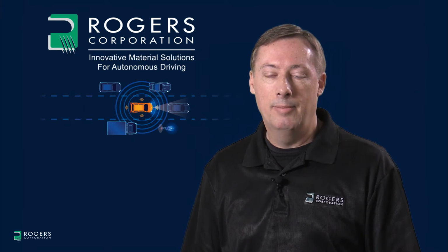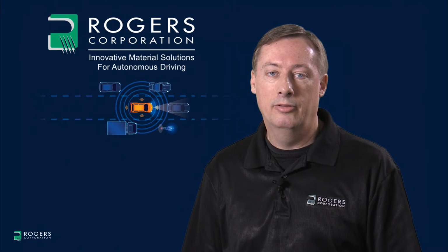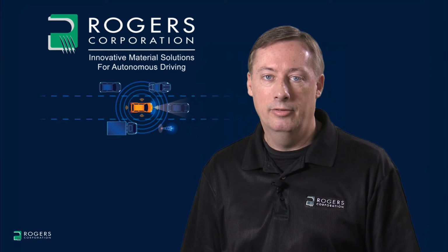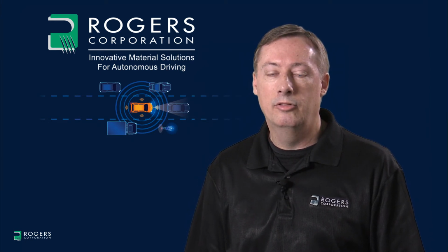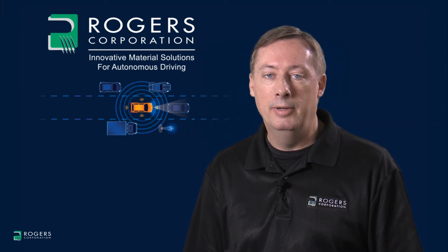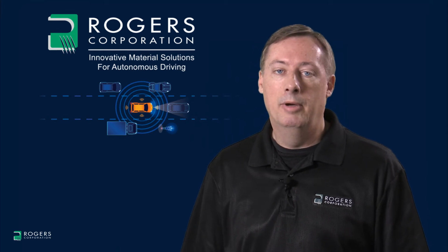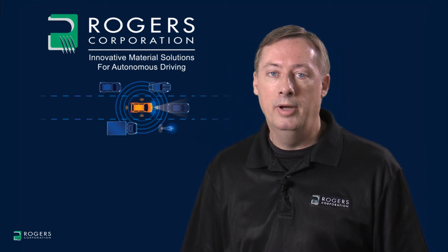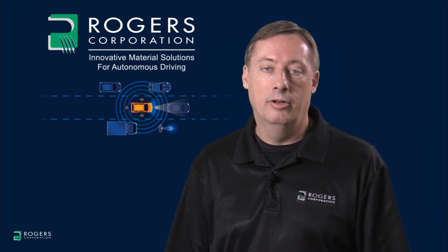We have done many studies on copper surface roughness and how it affects insertion loss and phase response, and this is essentially how the circuit perceives the dielectric constant in circuit form. So it's a circuit-perceived dielectric constant, which we call design Dk. From these studies, we found there are several things that can slow the wave propagation. In a general sense, once an electromagnetic wave propagating in free space enters a medium of higher dielectric constant, it compresses, but besides that it also slows down, and a slower wave is perceived by the circuit as a higher dielectric constant.